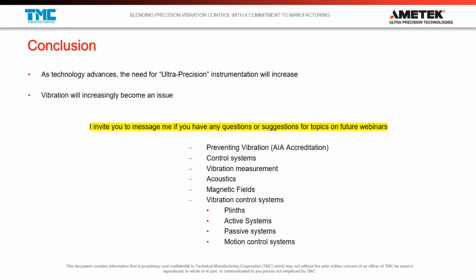Between vertical and horizontal vibrations, which source typically has a higher amplitude? Wow, that's a great question. Thank you. And there's really no way to say which one's more typical, because every vibration condition is different. And if you think about where you are in your building, you can have different floor vibration problems. Like, for example, in a high floor, in a tall, narrow building that's swaying in the wind, you're going to see very likely a low frequency horizontal influence.